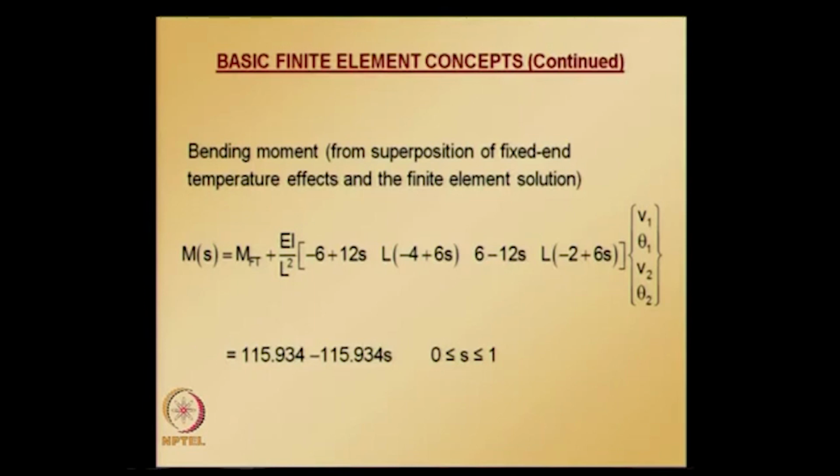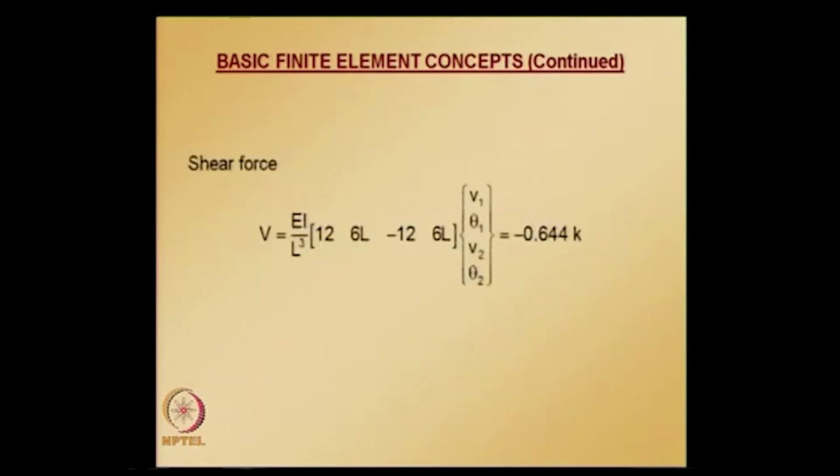Similarly we can calculate the shear force, but noting that because of the temperature effects no fixed end shear is going to be there, so no correction for shear force is required because of the temperature effects. The shear force is given by this formula, using the third derivative of the finite element shape functions for the beam element and the nodal values, and we get this shear force value.